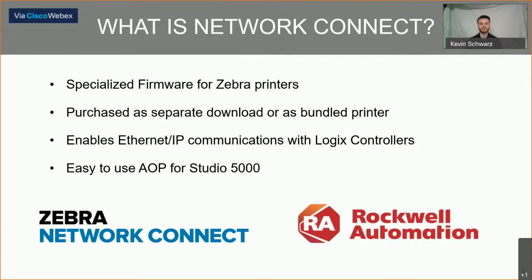Now, an important thing to note: this is only for the CompactLogix and the ControlLogix line of processors. For MicroLogix, you will still have to communicate over serial. So we're just going to focus today on the 5000 series of processors, being the CompactLogix and ControlLogix. Like I was saying, it allows for an add-on profile for Studio 5000. You can add it to your device tree just like you would any other I/O module.